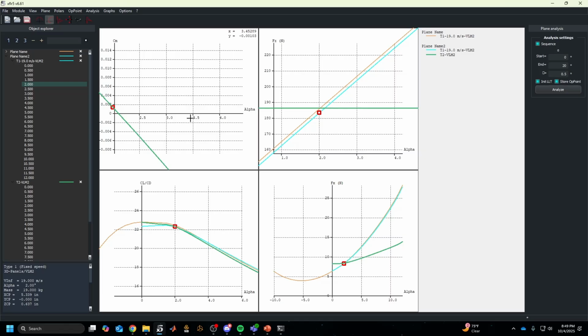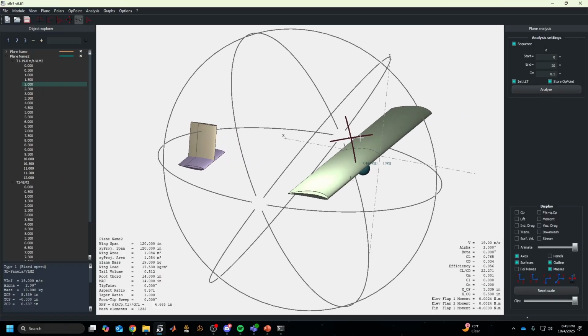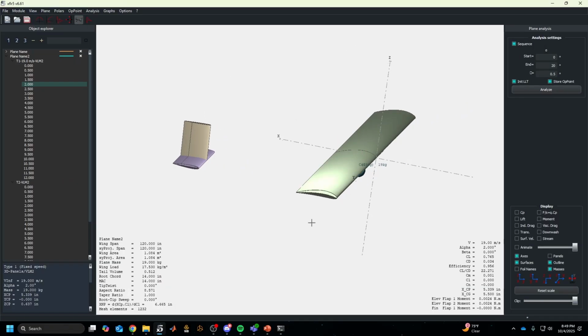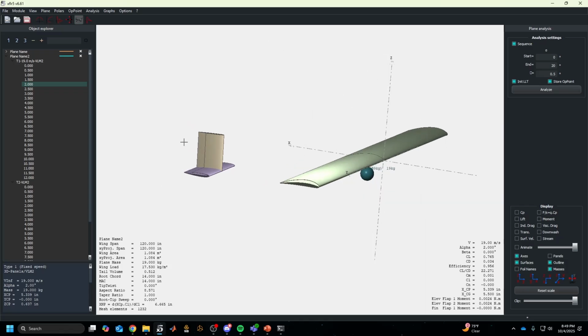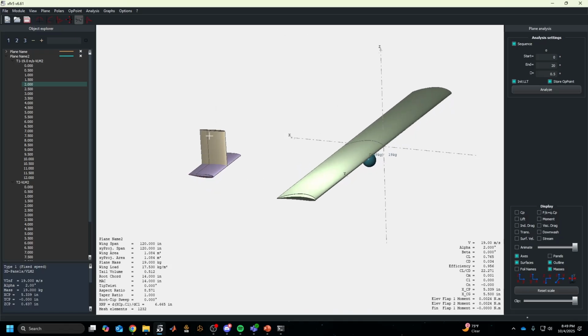So I think I did a pretty good job explaining this. Really quick, I'm going to show you guys how to do, not elevator, I'll do aileron deflections in this case. I don't have an elevator defined. You'd really want to use this for longitudinal static stability. You'd want to do your elevator deflections, again, to see that about a degree of elevator deflection is equal to a degree of pitch change. Okay, that was from the Aero and S&C lecture. Make sure you watch that if you haven't.